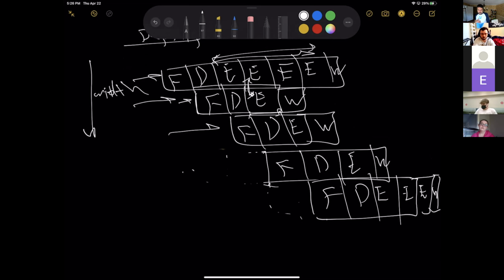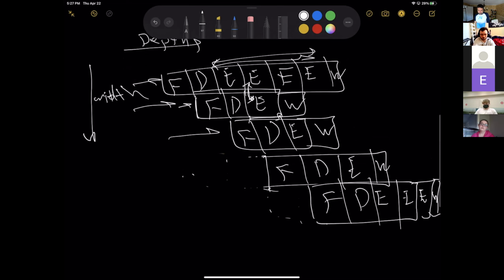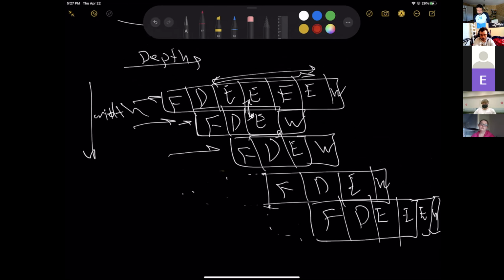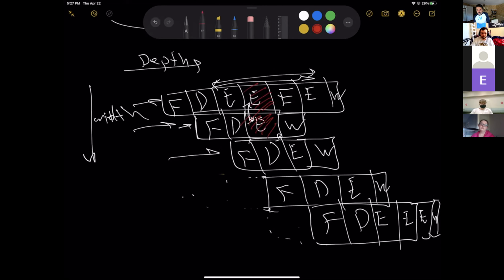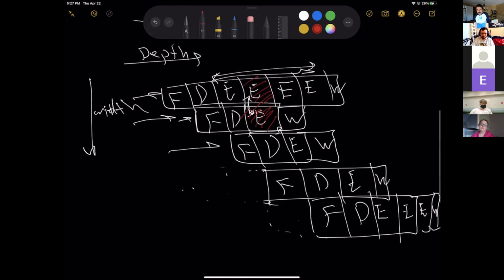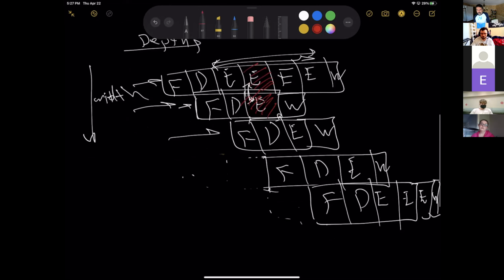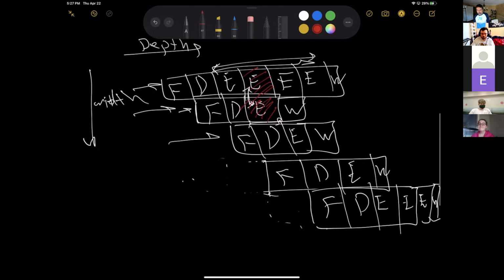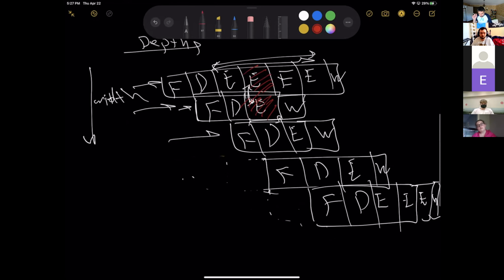Well, the reason I was saying about the column being occupied with two executions is that the ALU is already occupied in that cycle, doing the previous instruction. So that overloads it in that way. But in terms of instructions, the previous instruction hasn't finished, and if it's doing something with, let's say, S0, and the next instruction also does something with S0, the fact that the write for S0 occurs during the execution of the previous one causes an issue. That also has to do with S0. I don't believe I'm talking the right way.